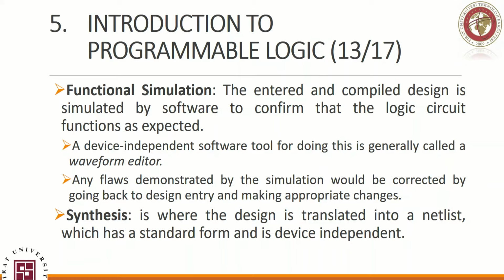Synthesizing is actually translating whatever compiled simulation we created into a netlist. A netlist is actually a standard that fits our own device. Why? Because for PLDs we may have some standard, for FPGAs we may have some standard, but the process of simulation, your functional simulation, is device independent. It's not dependent on the device. It's dependent on the software package that we are using or the text base of the programming and so on.